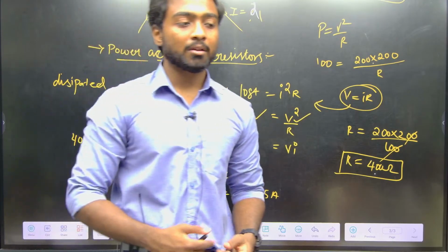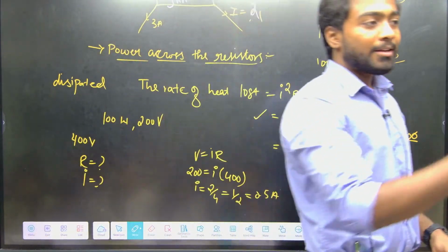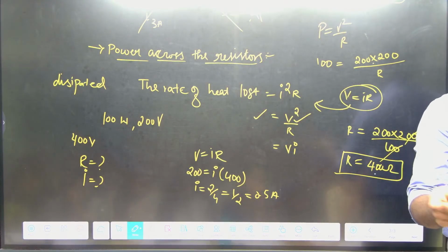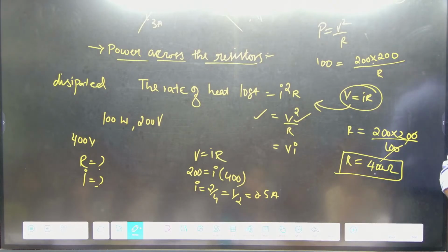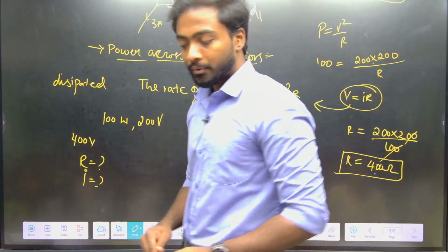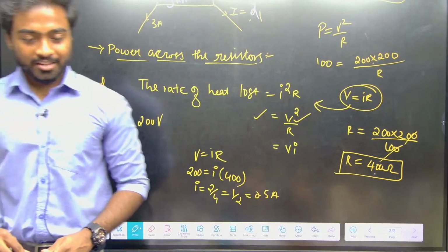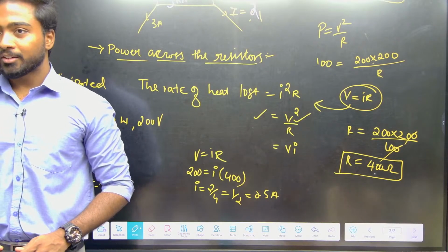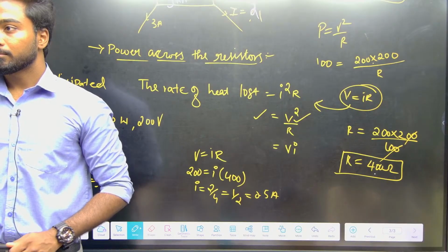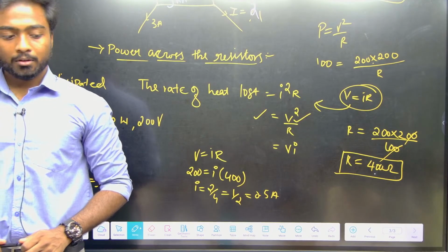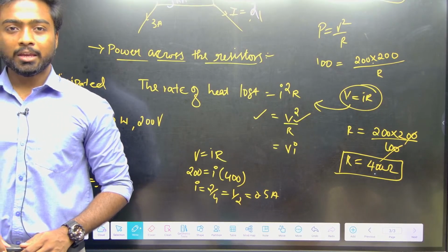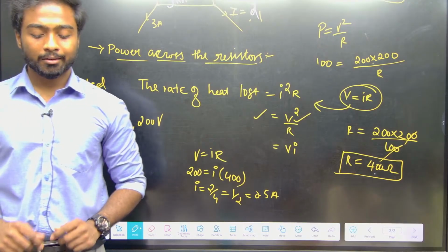So till now we were discussing the problems, no? If any junction is there, obviously I can take that as parallel, which means current has been divided at the junction. If current has not been divided at a junction, I can consider that as series. Second point: the equivalent resistance is greater than each resistor.